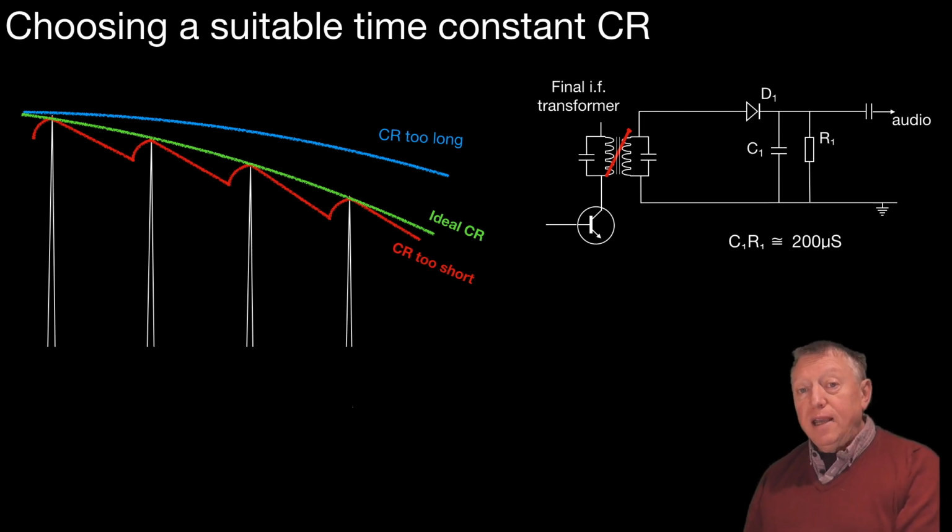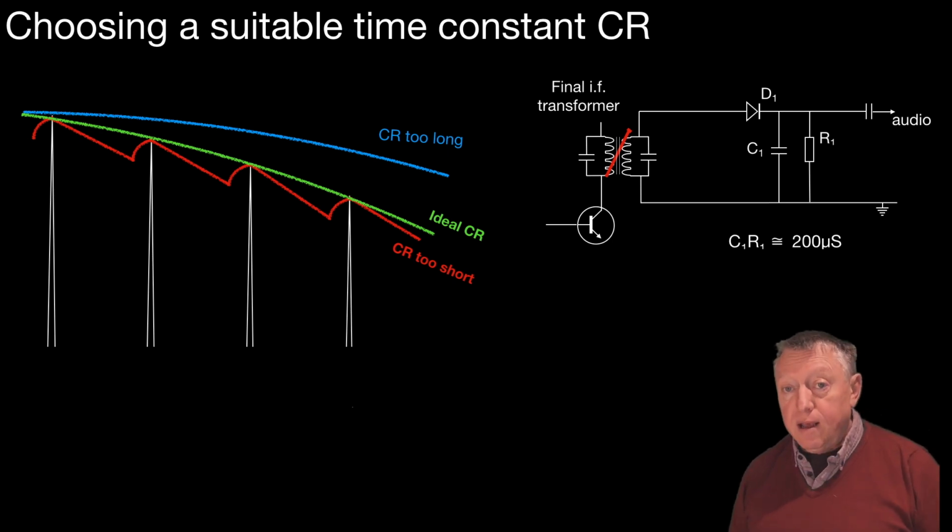And as there's such a difference in frequency between the top frequency, 3 kHz of the audio, and the 470 kHz of the IF, that shouldn't be a problem. We don't really have to worry too much about the differences between 300 Hz and 3 kHz, because that's not going to make a huge difference.